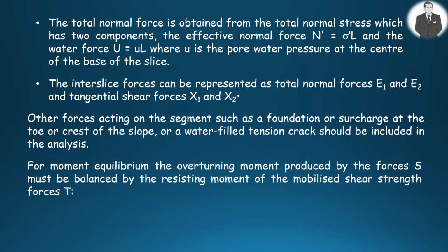For moment equilibrium, the overturning moment produced by the shear forces must be balanced by the resisting moment of the mobilized shear strength forces as formulated here. With the earlier expressions involved in this equation, it is modified as written here.